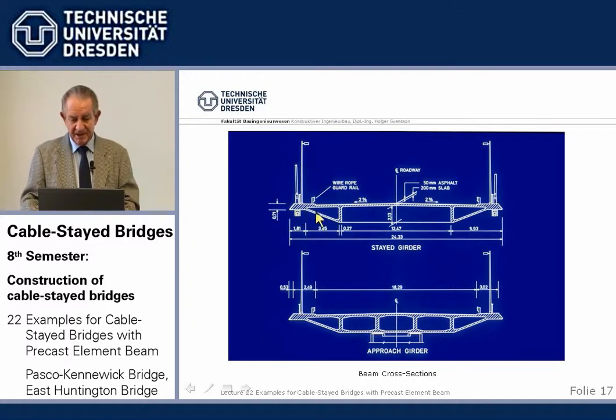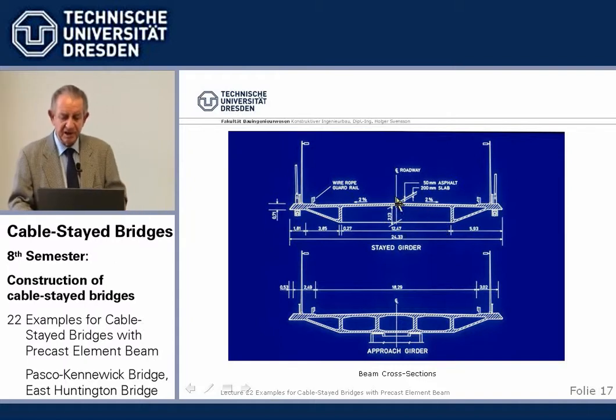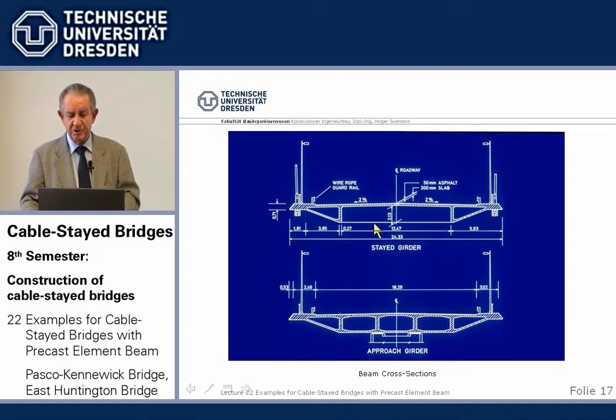And we have here these outside aerodynamically shaped, but there is no bottom slab because it is not required, and it was always an idea of Leonhard that you could do it without bottom slab, no box section here. It worked. It's not ideal. You have a little problem here at these points to get the stresses okay, but it works.